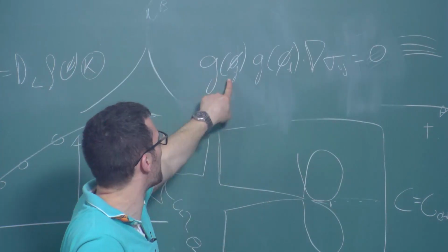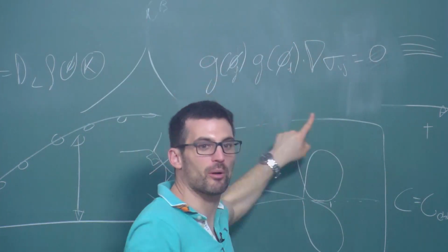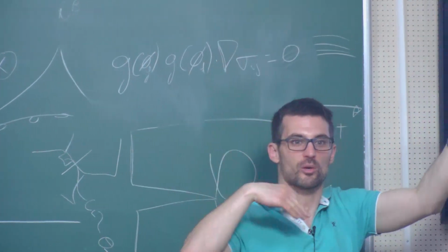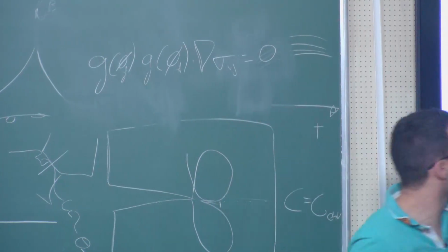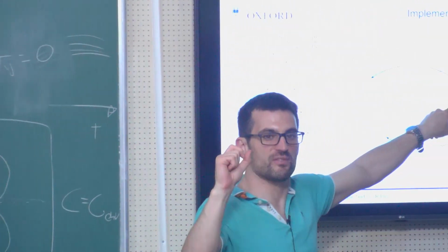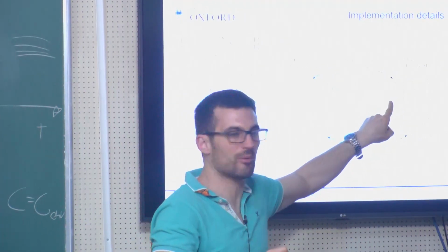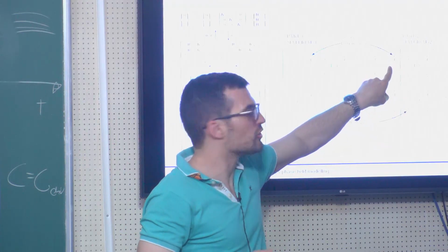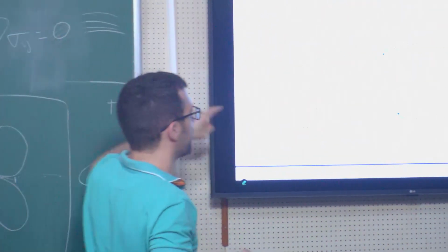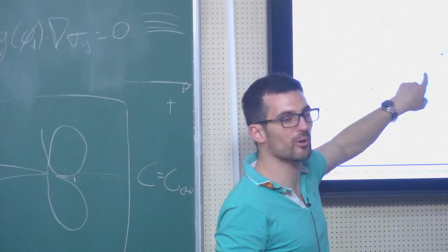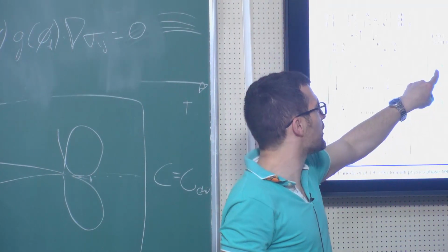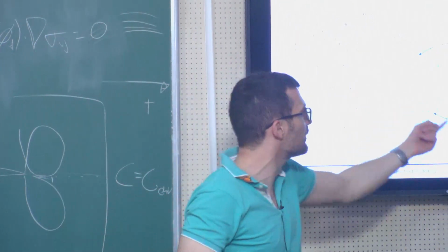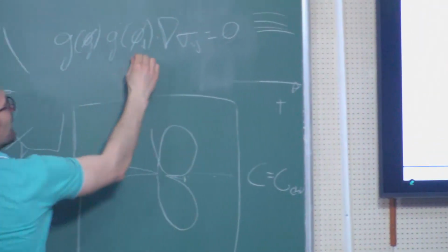So I'm solving the mechanical problem in part 1. I have this Fortran module that communicates between the subroutines. In that Fortran module, I stored, for element 7, integration point 1, the phase field corrosion value. Then when I'm dealing with my mechanical problem, in element 3, integration point 1, that is the equivalent, I say, okay, please take from that Fortran module where you store your phase field dissolution, take that value and plug it in here.